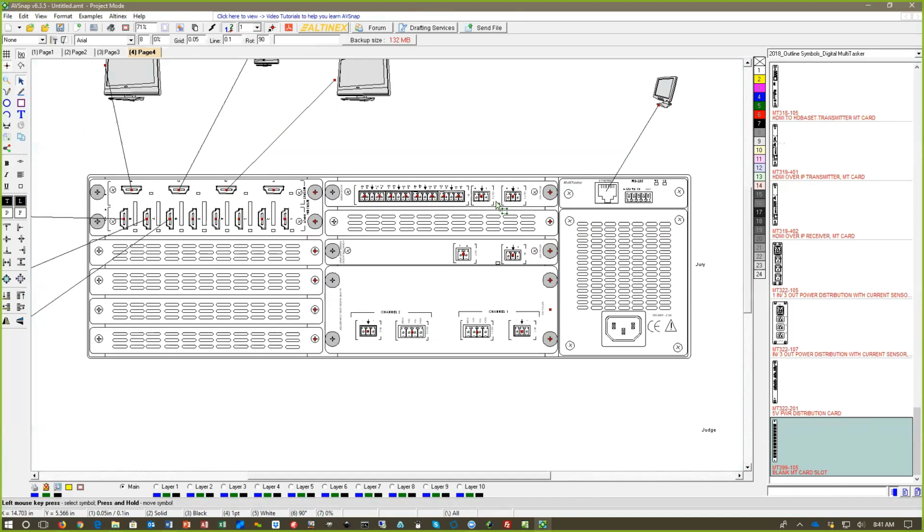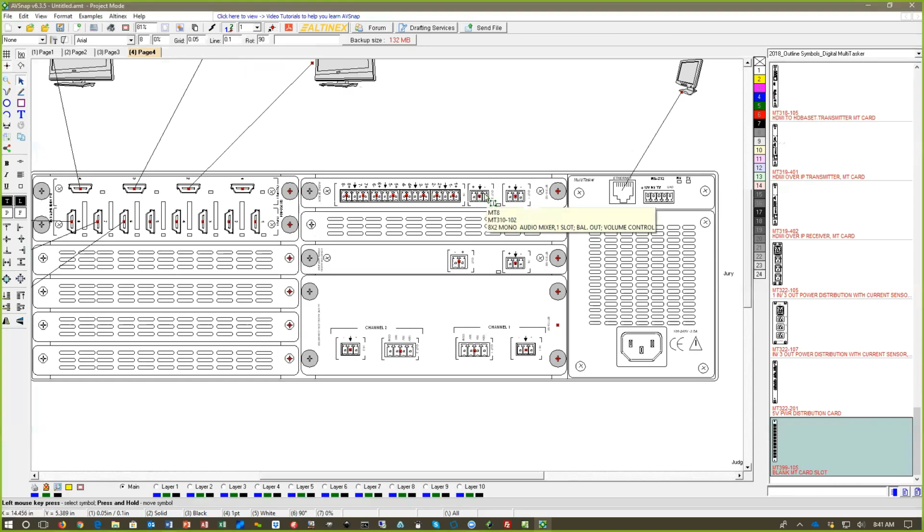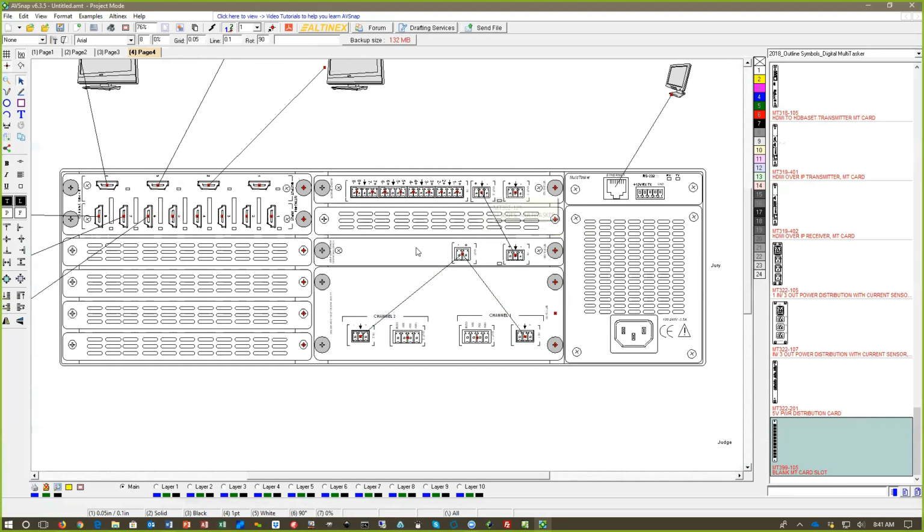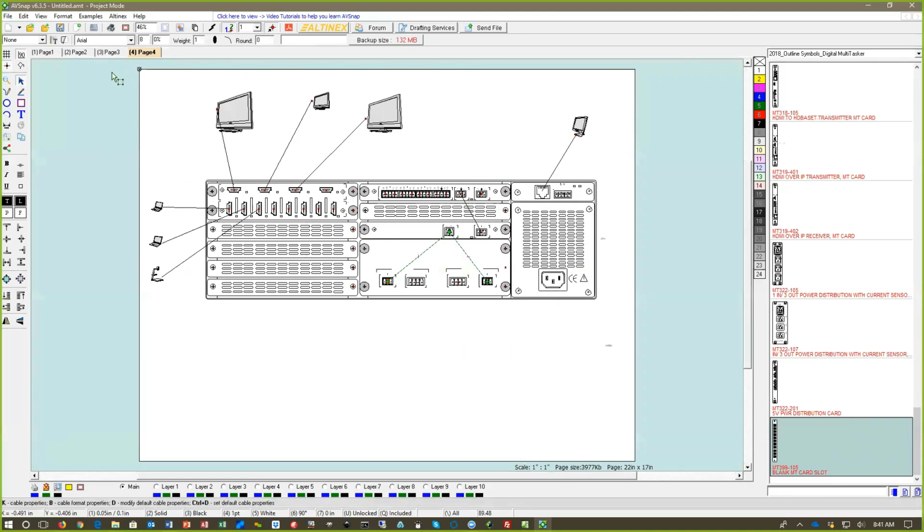The output from the audio amplifier will go into the mixer, so I can connect them here with the regular cable to the input. Okay. And then output from here will go to the level converter, and that will convert it to 70 volts. And there we're done. If we need more channels, we can put 2 amplifiers. This one is a 2-channel, but if you need 1 channel, you can use only 1 channel. All right, we are pretty much laid out here.